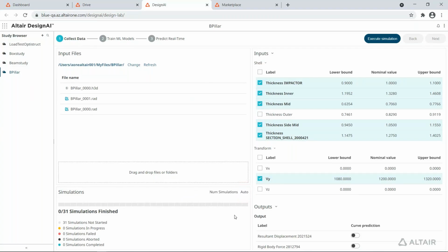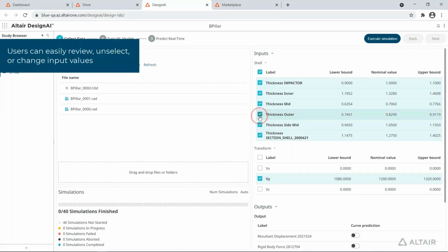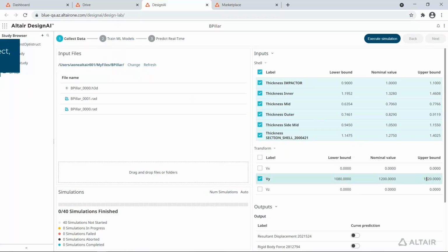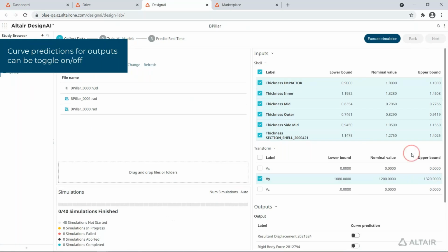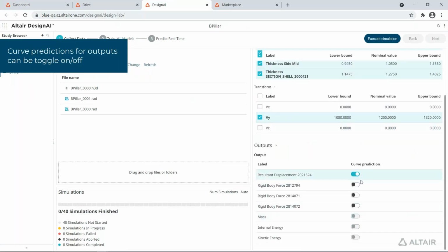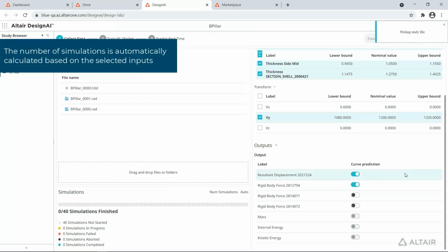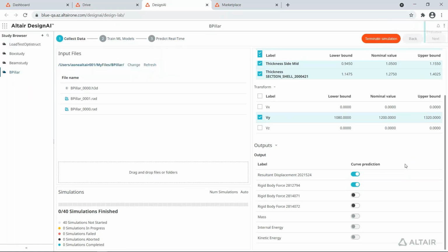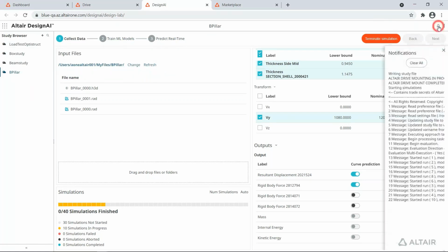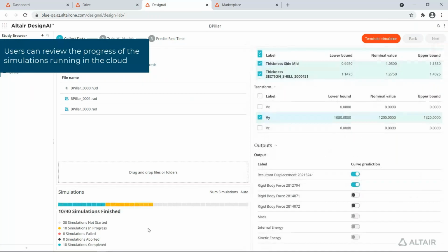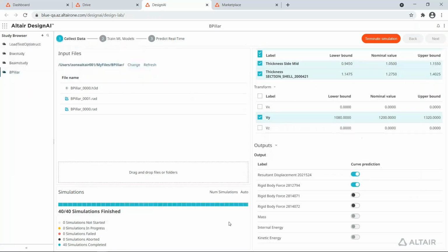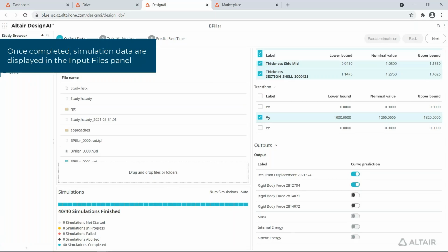You can change the inputs like lower and upper bound values, depending on your requirement. It may be a load value, a material value, or a thickness. Then execute the simulation, activate the outputs you are expecting or need, and run it. You can also check the solver window or output window. It has done some 40 by 40 simulations here.